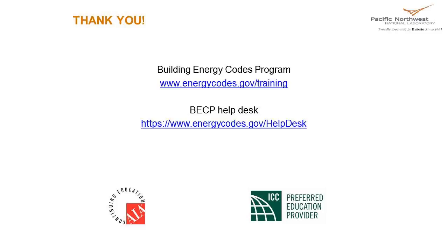And then the last one, the performance alternative. REScheck does have a simulated performance alternative I did not show you, and it is very, very specific to only solar gains, solar orientation, and overhangs. It is not full performance based. You would need to use a different tool that does a full performance based energy analysis of the building. That is not what REScheck does.